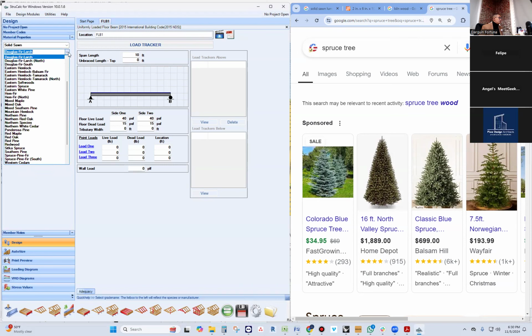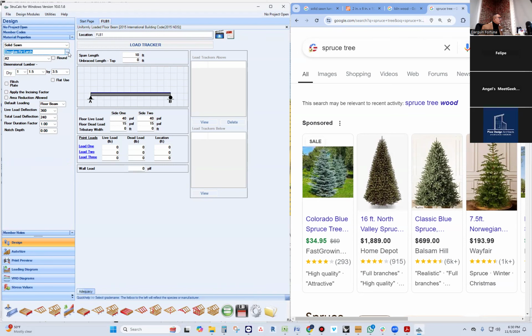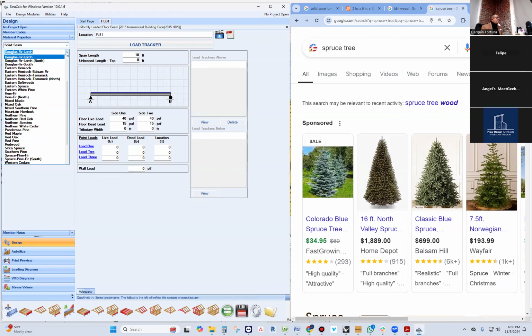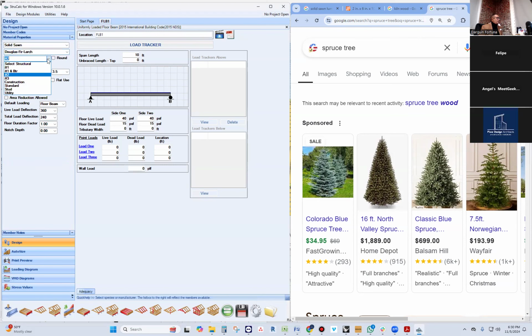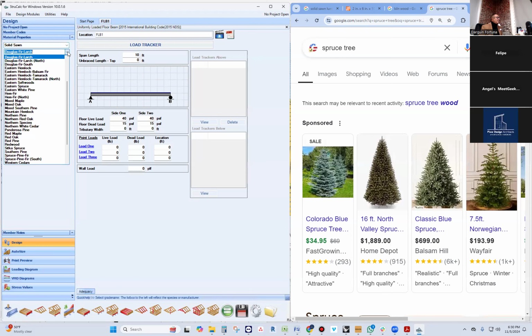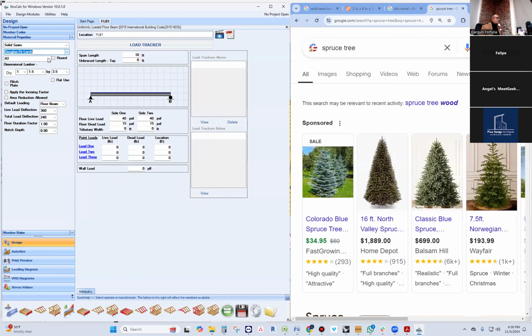So you can use either spruce in this case or Douglas fir. I want you to always refer to the default, Douglas fir. I think it's a good one. Now, type of material, type of species of the material, grade of the material. All right, let's memorize this. Type of material, type of species of a material, grade of the material. Grade refers to the quality of the material itself.